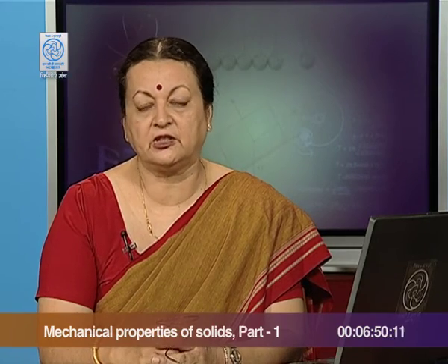You can measure the modulus of elasticity in the lab. You can do so for a wire, and you can also plot a stress and strain curve, meaning thereby you can find the value for strain in terms of original length of the wire that you have taken, place it on a rigid support, hang some load from it, a known value of load per se, and you can find out using a micrometer how much is the extension of this wire. So, extension of the wire, which will be your change in length, divided by the original length, which will give you the value for longitudinal strain in it.